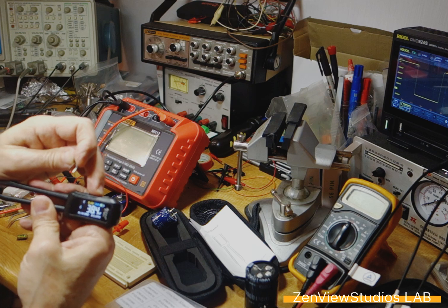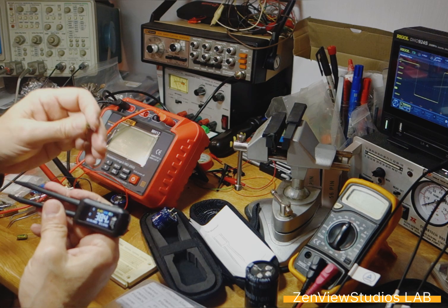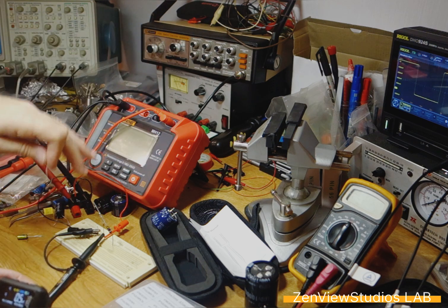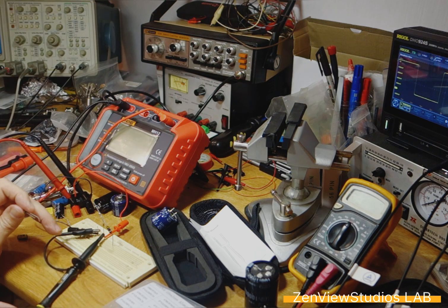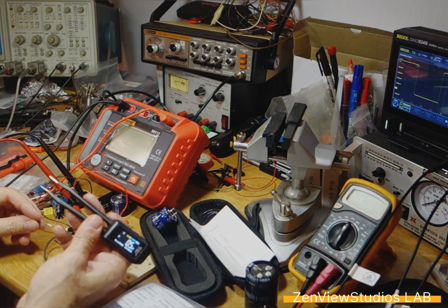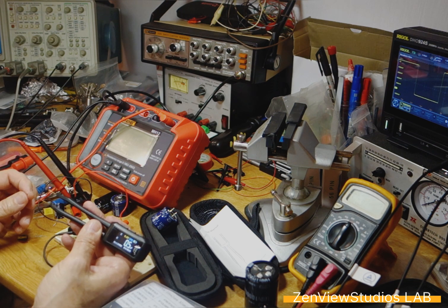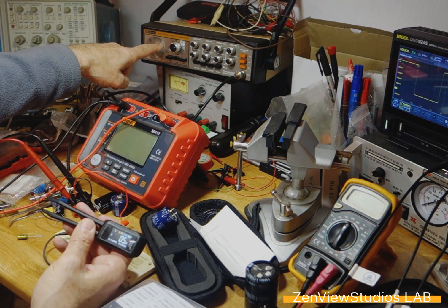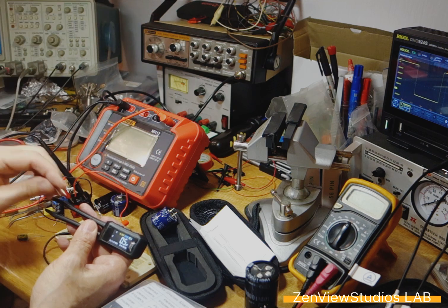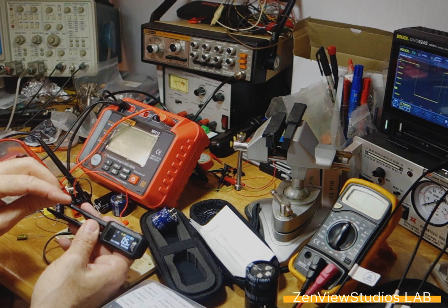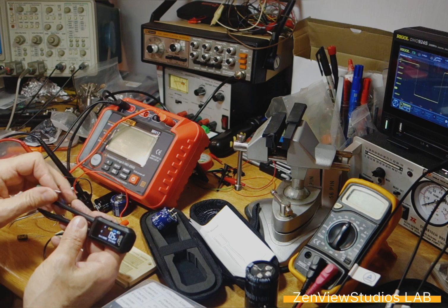So the interesting part was to find out if there was a correlation between the generator and this kind of measurement, where in fact you get the precision from the 5.5 digit multimeter, and compare with this. In fact, you do, but when you are at 10K and when I'm here at the generator at 100K. So that means for me, the measurement, even though it says 10K on the dial, is really made like a 100K measurement.